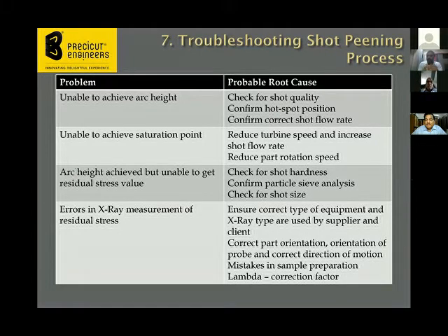But when the component is introduced in the process, the hardness of the component plays a critical role. To achieve the desired compressive stresses, the hardness of the shot should be greater than the hardness of the component. Then only it is going to create the micro dents required, and these micro dents eventually are going to generate the compressive stresses.